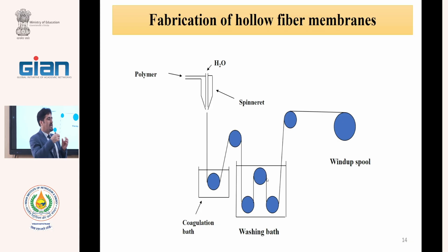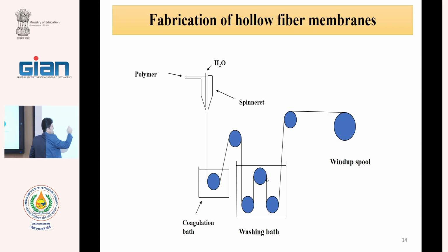And for this purpose, we use a non-solvent in the spinneret. And we first have coagulation inside of the spinneret. Okay? We inject this solution from here, but as injected in this place it will be contacted with non-solvent, and we have solidification here inside of the tubes.